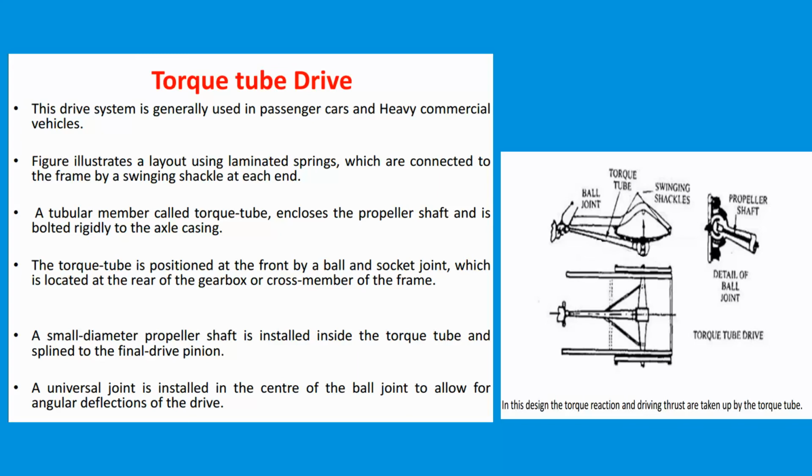In contrast, the Hotchkiss drive transmits the traction forces to the car frame using suspension components such as leaf springs and trailing arms. A type of ball and socket joint called a torque ball is used at the end of the torque tube to allow relative motion between the axle and transmission due to suspension travel. Later, the American Motors Rambler model used a flange and cushion mount in place of the ball and socket.